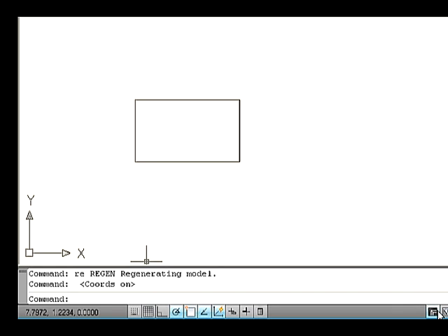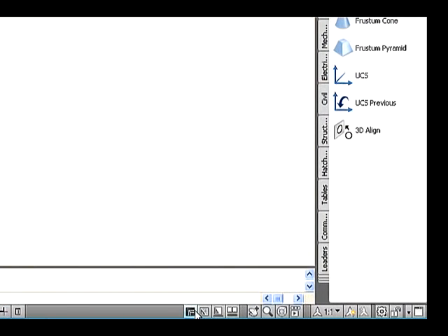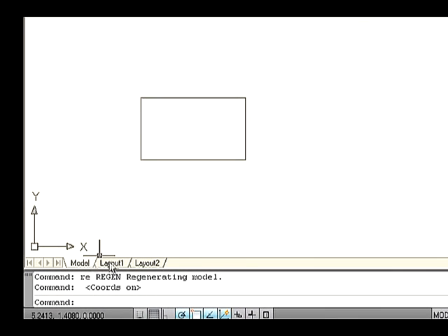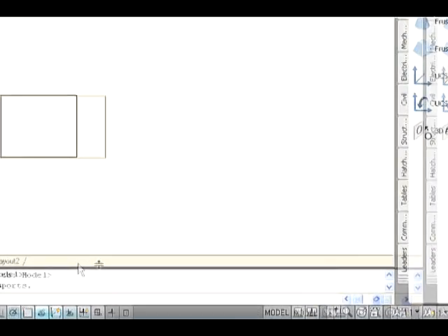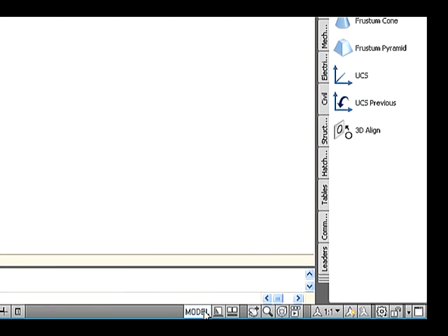Model button. This button is used to hide the model and layout tabs on the drawing area. To show the model and layout tabs, right-click on the mouse and select Display the layout tabs. The other options are similar to the older versions. Quick View Layout. It is a modern tab used to show the available model and layout tabs. It is very much used to switch between the layout tabs easily and reduces time a lot.